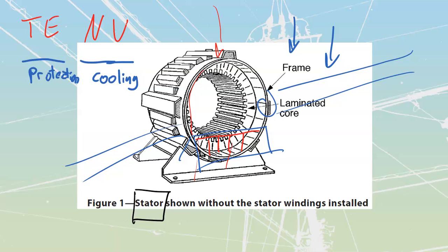They will get hot. You're going to have really good windings inside of them because they don't have any sort of ventilation. If you put these inside of an area where you've got high ambient temperature, they will cook faster than others because everything is going to be trapped on the inside. And if you go to too rapid of a temperature rise inside of these, you can also have other problems where you're going to end up with ruptures in the casing, blowouts in the bearings, etc., because you're just going to increase the heat inside, which is going to increase the pressure, which is going to give you your mechanical issues.